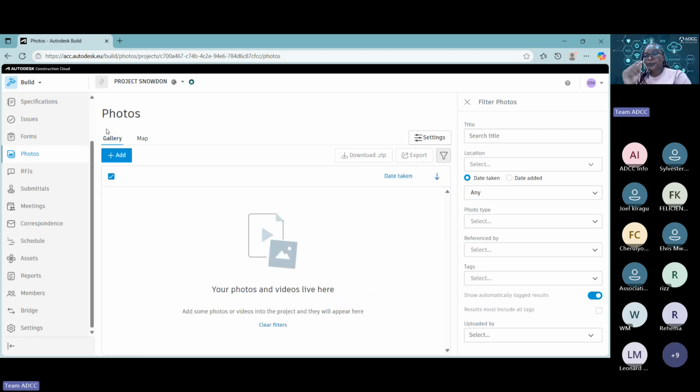When you're setting up your project at startup, you would log the specific location of your project. So even when you're on site and using your phone, I would suggest that those using photos in Autodesk Build use the ACC on their mobile phones and make sure that your geolocation is on. As you take photos, upload them and they're synchronized to the app, it will pick those different pins, and you'll see on the outline on the location map the various photos that have been taken based on where you are standing on the site itself.